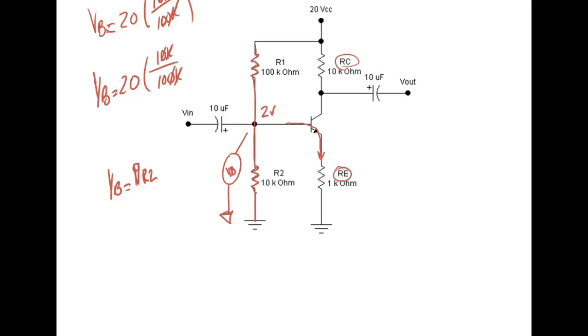Now, of course, this is easy, but you find out most of the time, with a two-resistor circuit, a lot of times you can do RT in your head. Sometimes, if this was 470 and this was 47 down here, it would be the same ratio, but now you're going to have to do math, right? You probably have to get your calculator. Okay, so that's 2 volts.